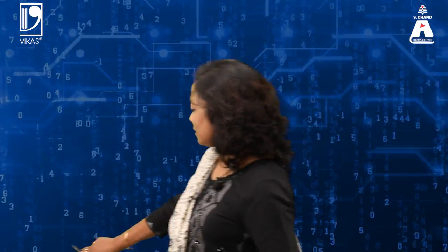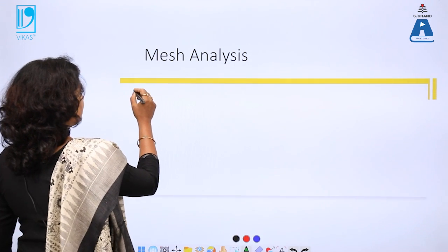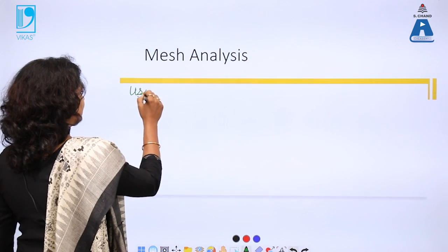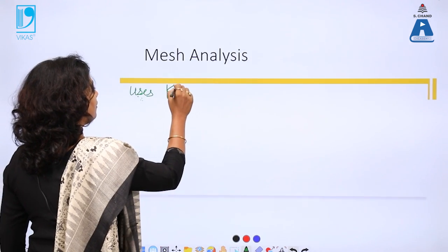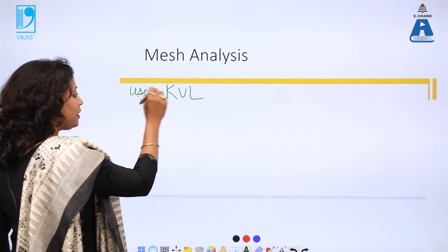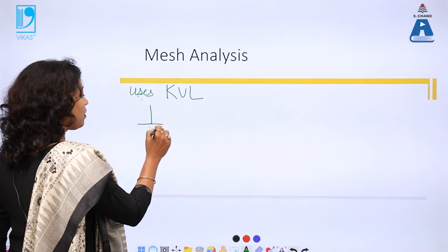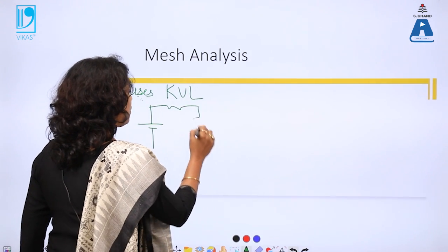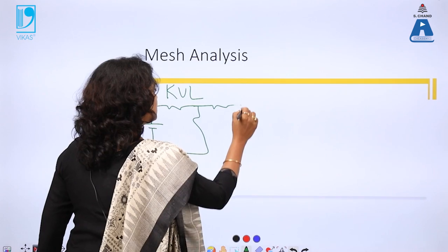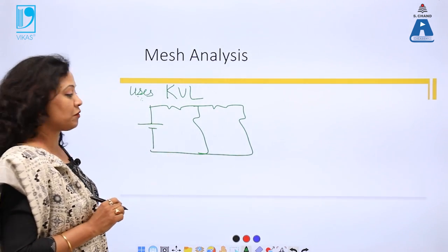And today this lecture is all about mesh analysis and nodal analysis. So we'll start with mesh analysis. Mesh analysis uses KVL, Kirchhoff voltage law, where we find out voltage in a loop. So this is analogous to using Kirchhoff voltage law. There is a certain difference in using mesh analysis and using Kirchhoff voltage law.